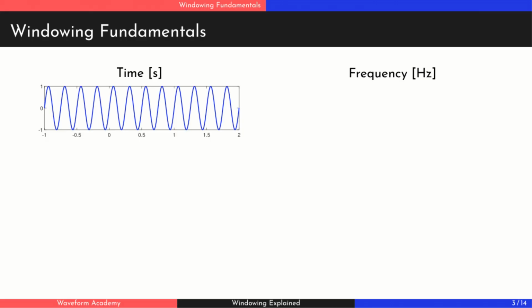Let's begin with a simple signal, an infinite continuous sine wave at 4 Hz. Its spectrum contains just 2 sharp spikes, called Dirac deltas, at -4 and +4 Hz. But here's the problem. You can't record an infinite signal. In practice, we only capture a portion of it.